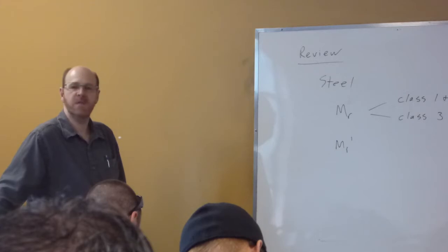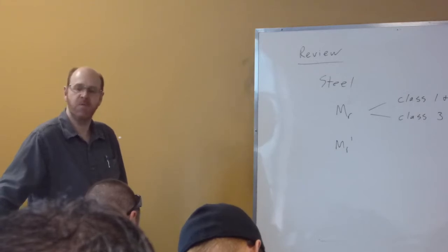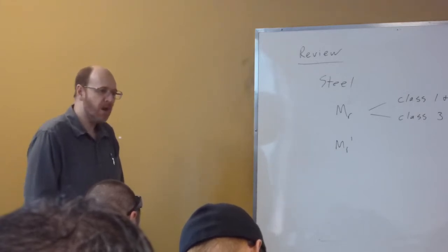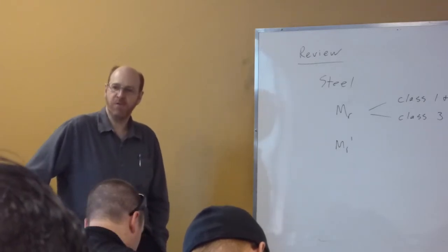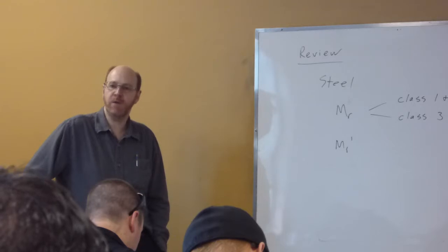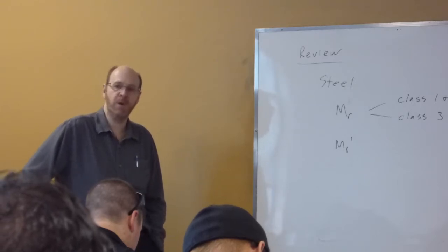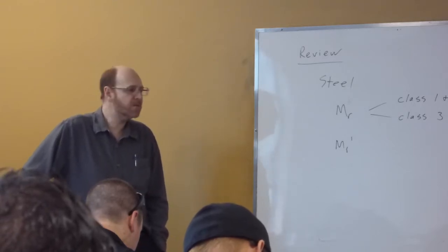So since a lot of the steel that we get in Canada is based off or imported from the States, if you're ever doing any calculation by hand, you're going to use 345 MPa because we don't know necessarily whether it's from a Canadian supplier or an American supplier. So 345 is on the safe side.